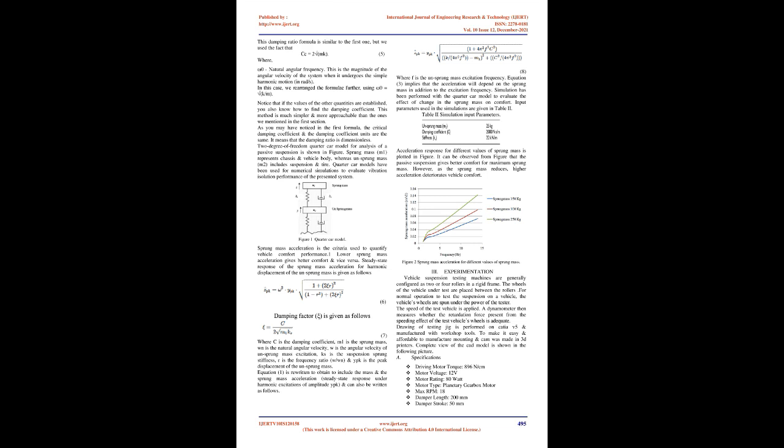Spring rates typically have units of N/mm. A nonlinear spring rate is one for which the relation between the spring's compression and the force exerted cannot be fitted adequately to a linear model. The spring rate of a coil spring may be calculated by a simple algebraic equation, or it may be measured in a spring testing machine. The spring constant K can be calculated as follows. K equals d^4 G / 8 N D^3, (2), where d is the wire diameter, G is the spring's shear modulus, e.g., about 80 GPa for steel, N is the number of wraps, and D is the diameter of the coil.